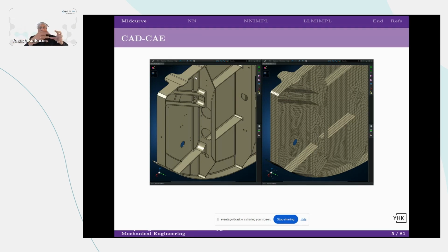Instead of multiple nodes on each brick, you have to solve for all of them. Computation is more. When you create a surface in the middle, called the mid surface, and do surface meshing, the number of nodes is less, calculations are less, but results are equivalent. I'll show you the comparison. By the way, you may or may not follow whatever I'm speaking as of now, but just bear with me, because this is how we are converting a machine design, mechanical engineering problem to a graph-based problem.